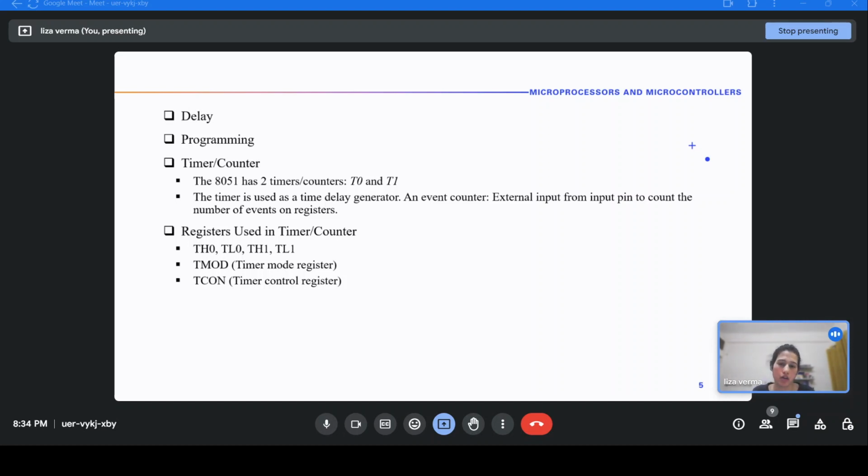It enables that hardware control. You connect your button to the INTX pins, which, if GATE is set, enables that button to have control of starting the count.